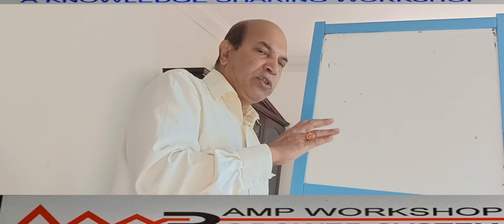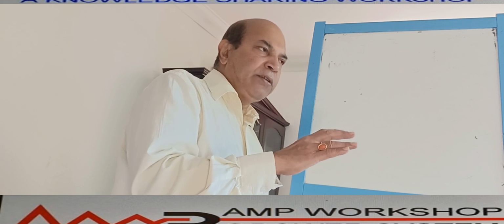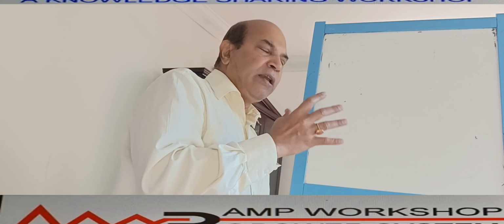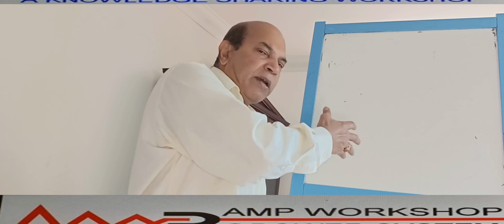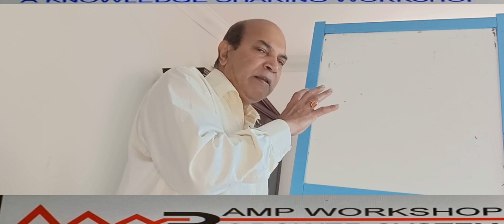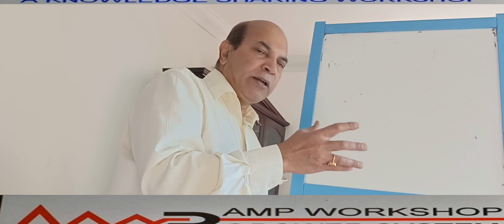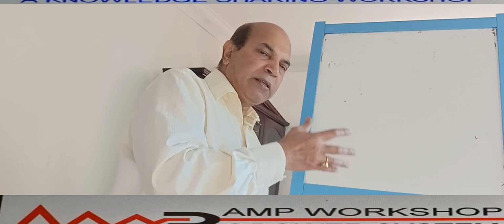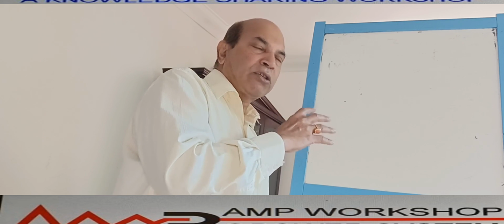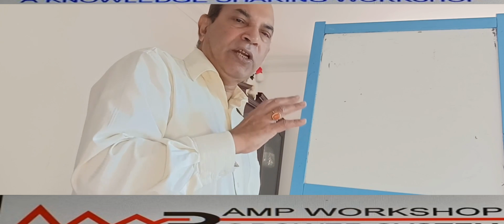So in brief, up to this point under session 7, in the first video, we elaborated on impedance: how it can be represented, what the meaning of impedance is, what the components of impedance are, and how the components are related. If you want to calculate the parallel impedance, instead of 1 by Z, we can use conductance and susceptance; the relation between conductance, susceptance and impedance was also demonstrated in the first video. In the second video, we calculated a typical network's short circuit current by the ohmic method, converting the impedance of various equipment and cables into absolute ohms at that particular voltage. And in today's video, we calculated the short circuit current using the per unit impedance. With this, our symmetrical short circuit fault current calculation is completed.